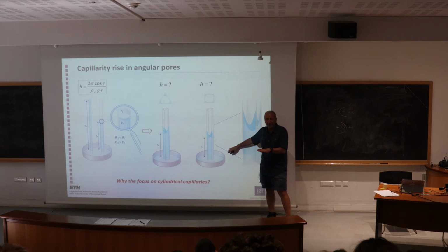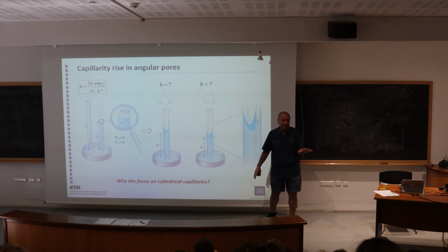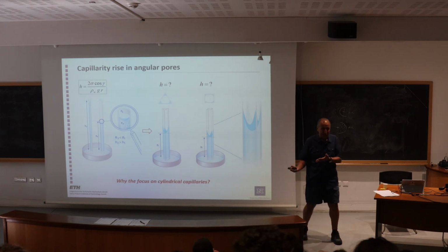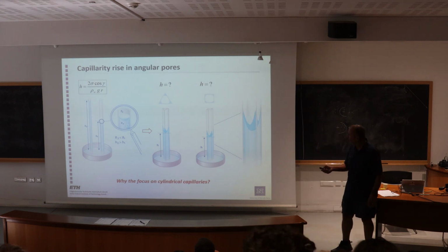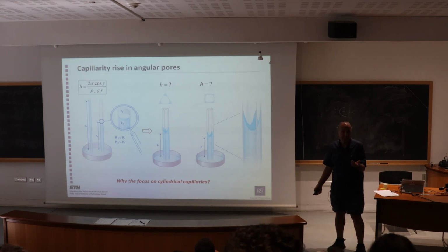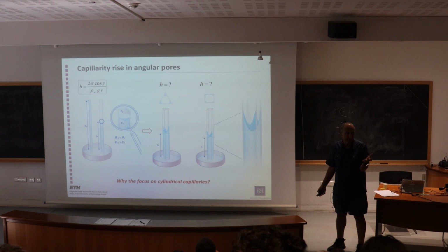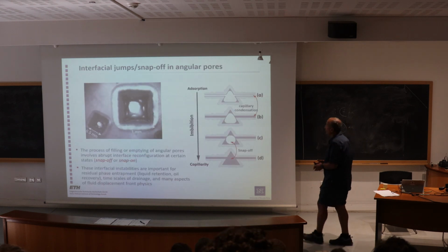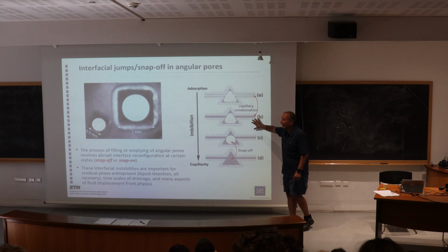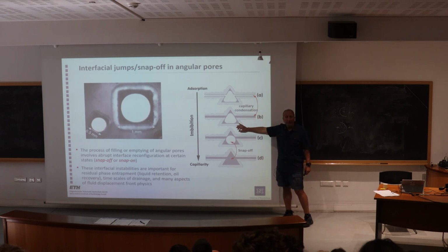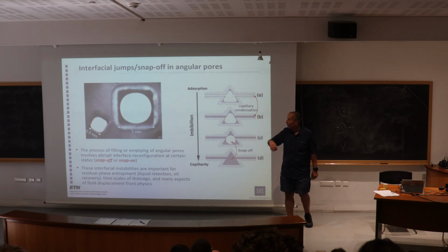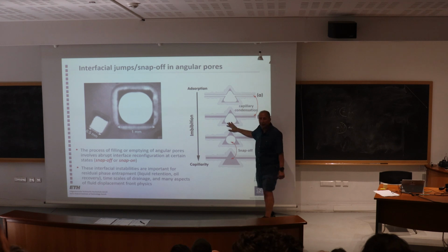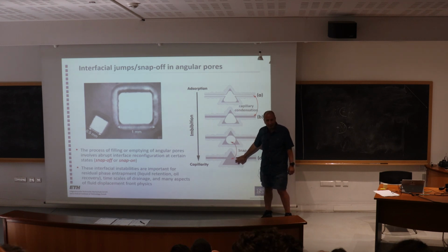In the next 2 slides, you'll never worry about angular pores anymore because they are so simple. I'd like to look at capillary rise in pores with cross sections, square or triangular, or any shape actually. A few things about angular pores: unlike cylindrical pores, angular pores allow coexistence of liquid and gas within the same domain.